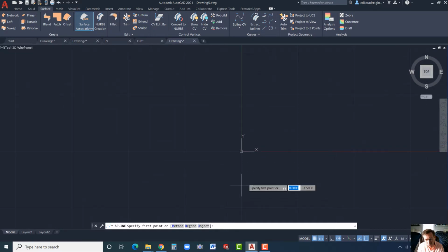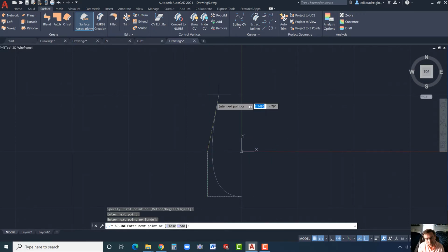Now zoom out enough to where we're below the Y in the negative direction, about 2. See, it says -2 and it's snapping. Click and drag it over about 1.5. Click and drag it directly above here, so polar is 2 inches and 90 degrees. Click, and then bring it up here, and we'll have it go to right about there, and then straight down.